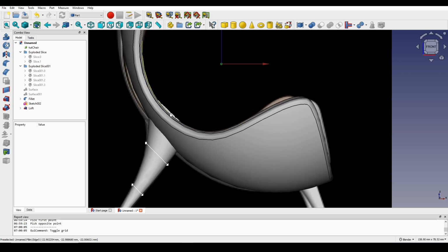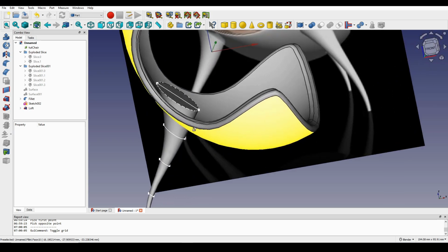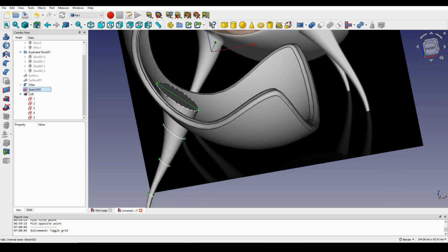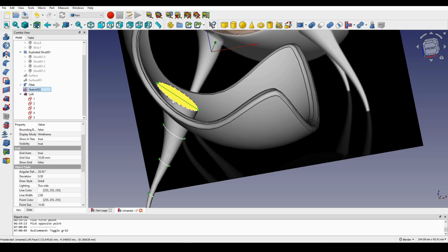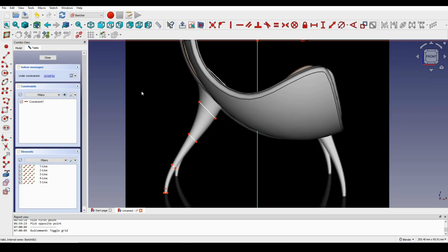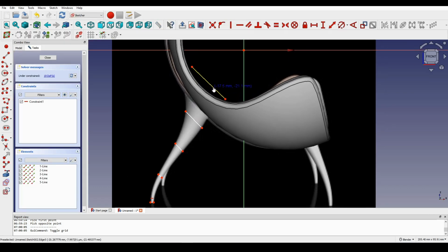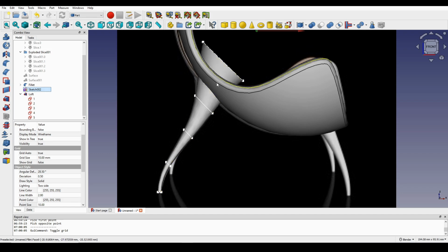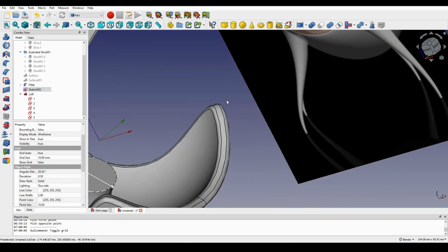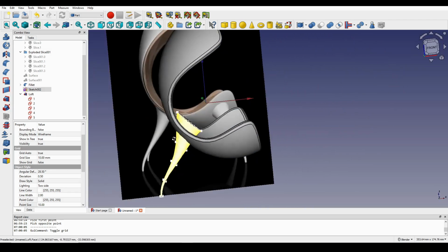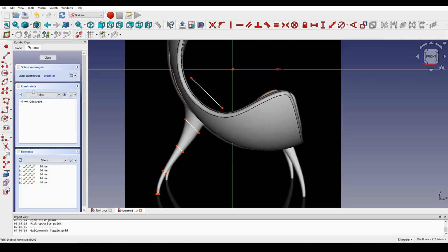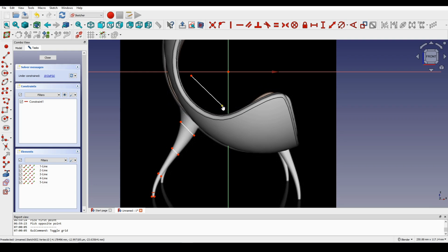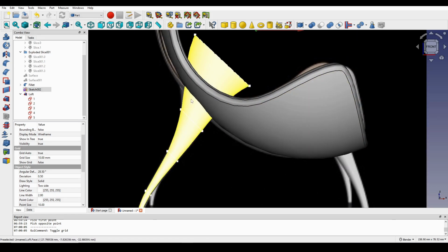The cool thing about this technique is that you can go back, and let's see, in the sketch 002, there are a bunch of lines, right? So if you go in the sketch 002 and you change the position of the line and also the shape of the line, I close that. The loft also updates the width, the position, and the height of the ledge, right? So maybe I should move this one up a little bit, something like this. I close that and you can see the shape also changes.